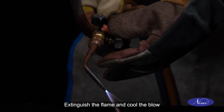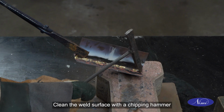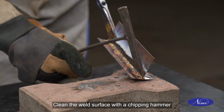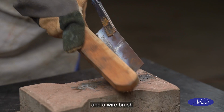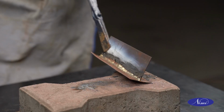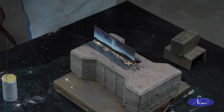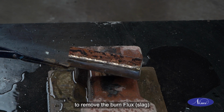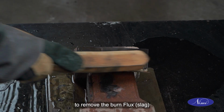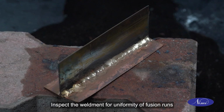Extinguish the flame and cool the blowpipe in water. Clean the weld surface with a chipping hammer and a wire brush. Cool the job slowly. Clean the job with hot water to remove the burnt flux, slag. Inspect the weldment for uniformity of fusion runs.